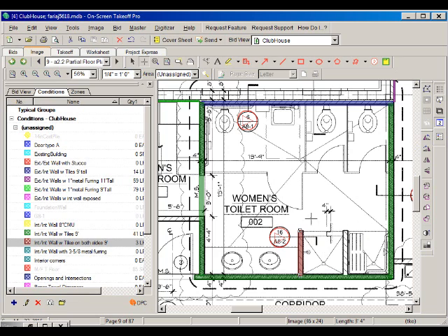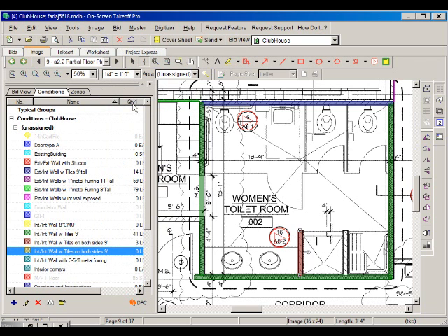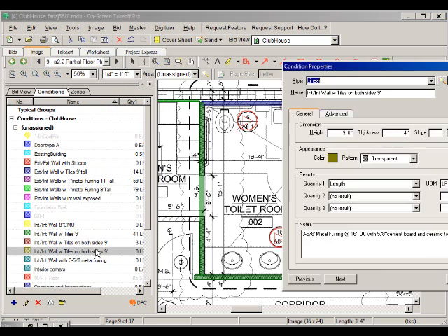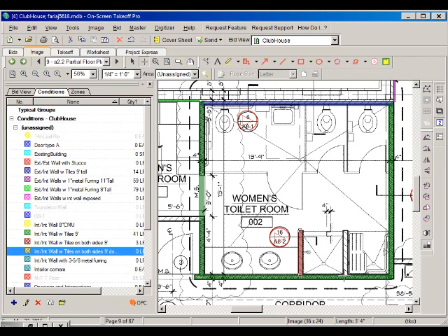And then basically we measure this here. This is going to be with tiles on both sides also, but this one is going to have double reinforcement. So both sides, double studs. So this has metal furring at 20 inches on center, metal furring double at 20 inches on center, and then ceramic tiles on both sides, 9 feet high. That's the one. So we measure this wall here.